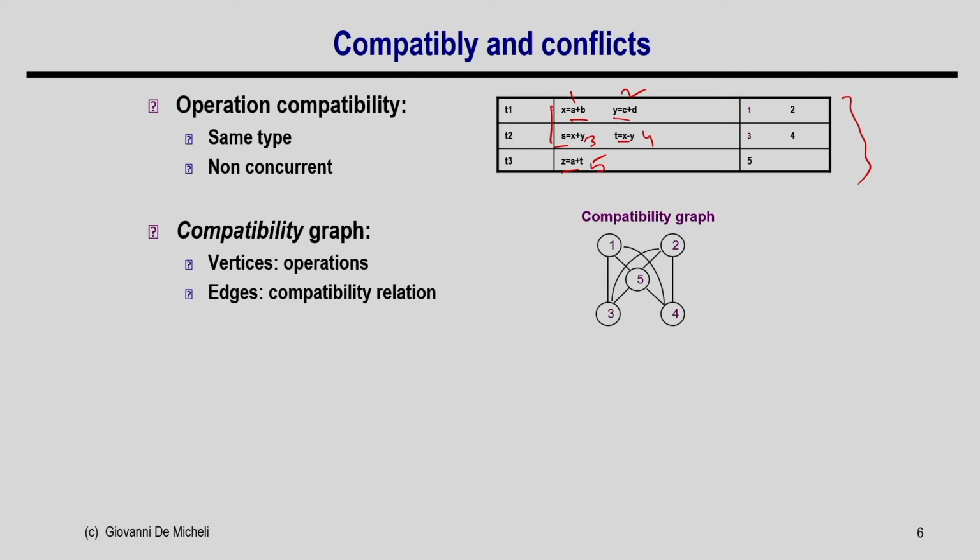That ALU will perform operation 1 in time step 1, and in the next clock, in time step 2, it can do operation 3. So, once two operations are scheduled in different time steps and are of the same type, they are compatible with each other.